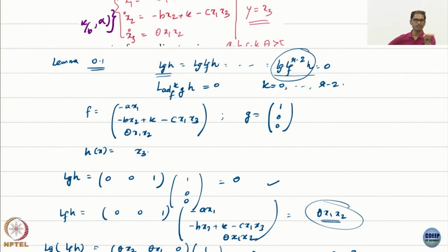In the case of robot dynamics, it's fully feedback linearizable, right. So it actually behaves like a double integrator, it behaves like a linear system, particularly easy to control, particularly easy to work with. Other than that, I don't know of any other physical relevance. And controls folks attach physical relevance to sensors and actuators, right. So if there is a linear connection between the sensor and actuator, we really love it, right.